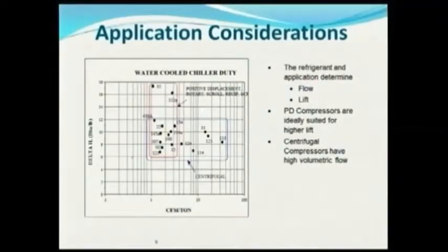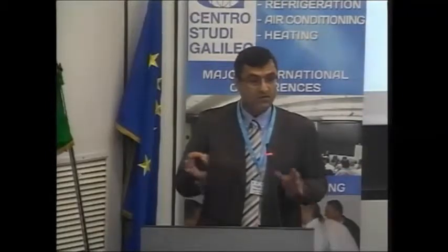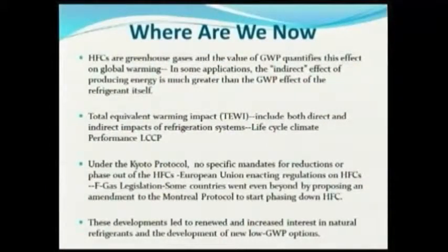Refrigerants also depend on the refrigeration that we're looking for. Some applications require high flow, and some require high lift, so it depends on where the refrigeration is. Some need a lot of CFM per ton, so we talk about certain refrigerants. For high lifts, we speak about different refrigerants, and so on. So where are we now? What's the situation right now? HFCs are greenhouse gases, and they have GWP effects.